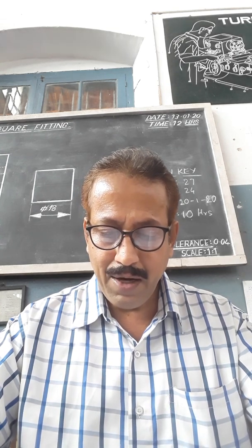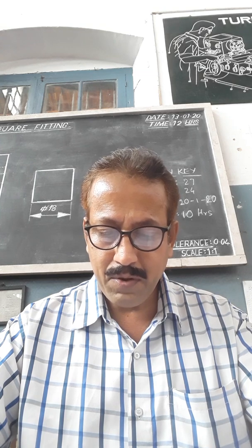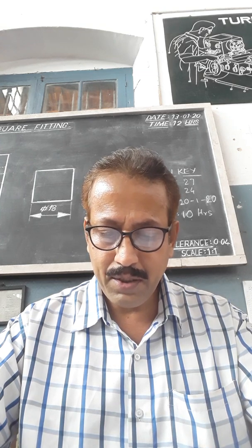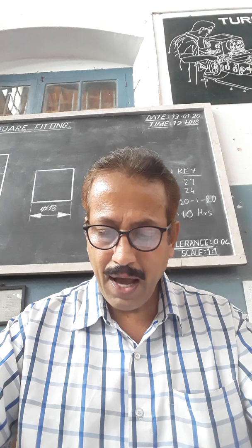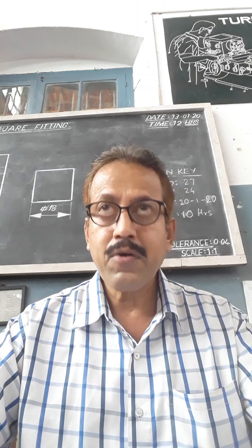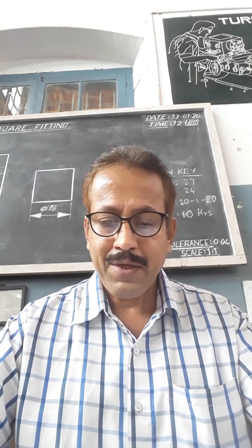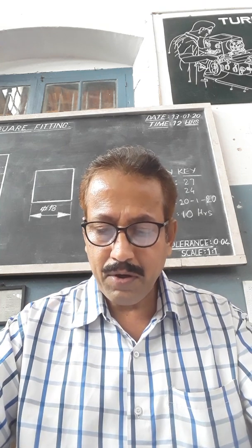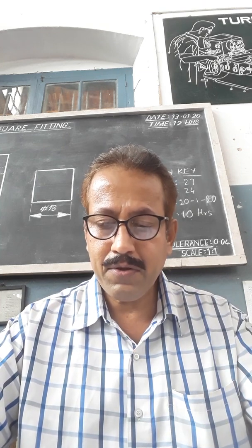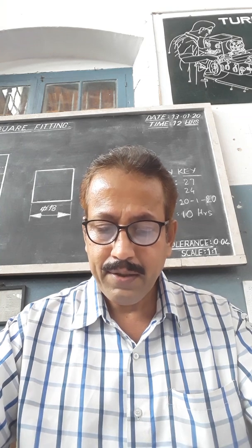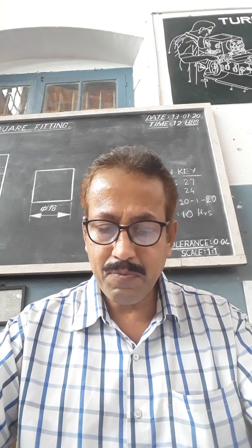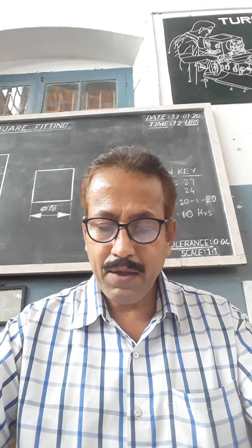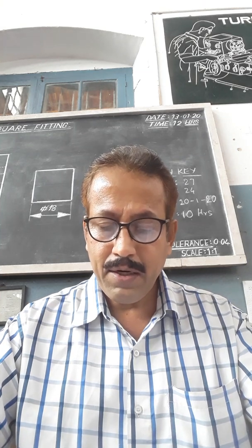Second one, if the arc of contact is insufficient because of the short center distance between the pulleys, a jockey pulley should be introduced as near to the small pulley as possible. So the second point is, if the center distance between the pulleys is very short, then a third pulley is used, that is the jockey pulley. This pulley is used near the smaller pulley to put the belt under more tension and to have more